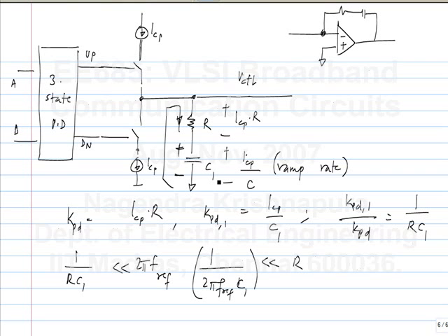Okay. So we will not worry about that. This is the simplest realization because you have up and down. To get the difference, you simply have current sources connected to the node. That's the simplest way of getting difference in the analog domain. Difference or summing. You sum currents. In this case, currents are of opposite polarity, so you get the difference, up minus down.